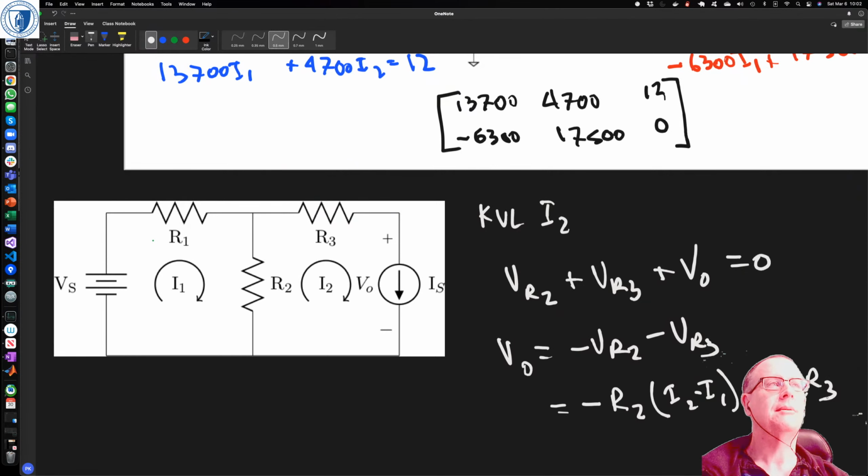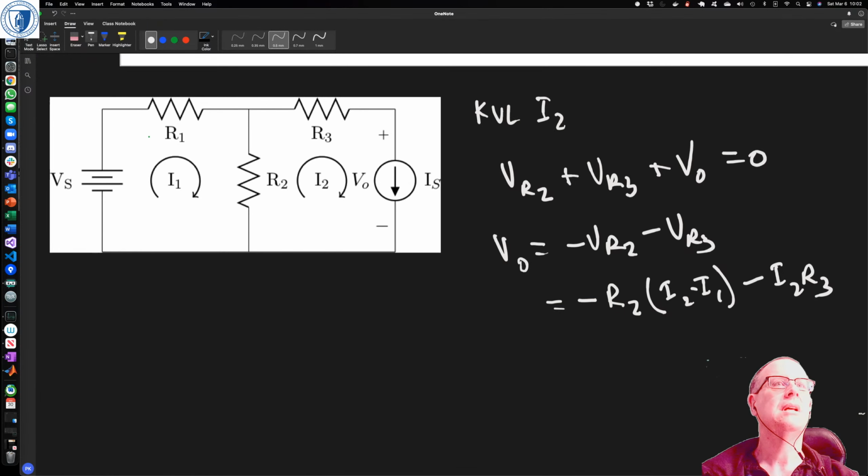Okay, and that's that. Can't see what you're writing because it's kind of covered. Sorry. Can you explain again, please? So, you can. Kirchhoff's voltage law still holds, right? The only reason we can't use the Kirchhoff's voltage law equation to do mesh analysis when there's a current source is because we don't know what V out is. So we use KCL instead, right?